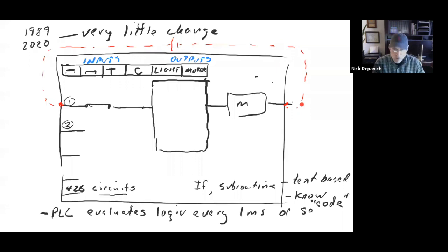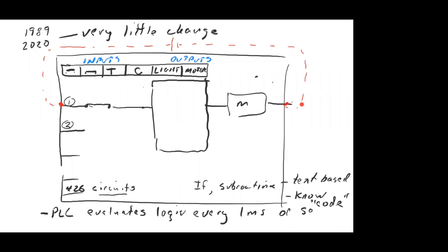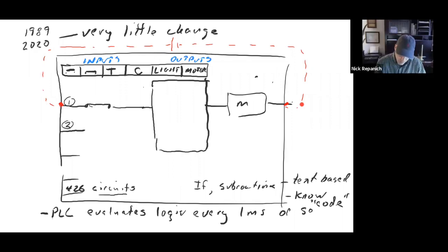Okay, so we did timers. Oh, we did switches, outputs. We got one more. Counters. Counters, right. So we had the counter. Okay, so why don't we make a counter? I guess I could have left it that color, but let's make a counter. Okay, so a counter and timers are both, now we've moved into the PLC library, those are both function blocks. So we want to go get a counter function block.